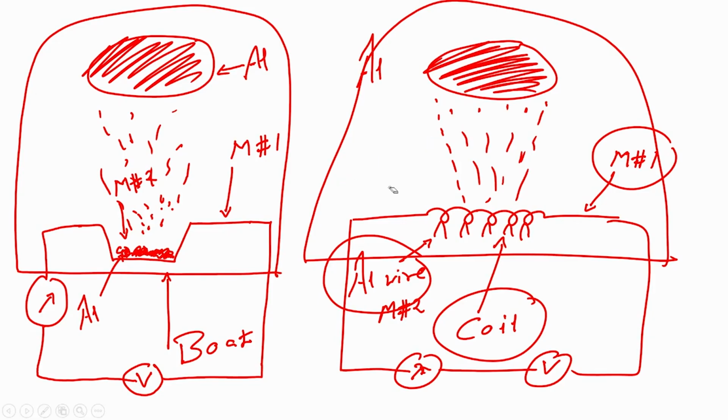Because we want to have a very high mean free path. If the mean free path is higher, we will have a better deposition with less collision between the atoms when they are going from solid to melted, liquid or semi-liquid, to vapor, and finally getting deposited on the substrate.